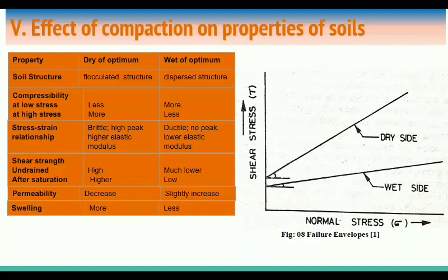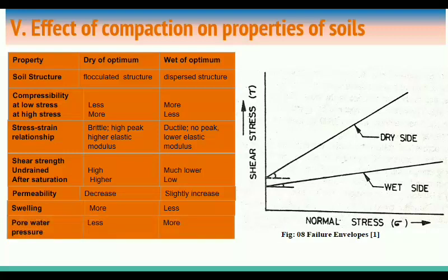Swelling. Swelling is more on the dry side of optimum because the water deficiency is more on the dry side of optimum. Pore water pressure is less on the dry side of optimum because the water content is less.